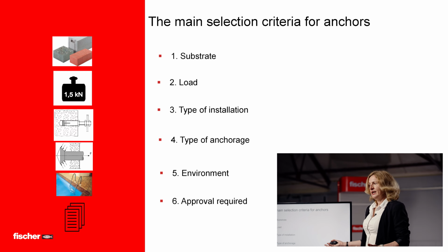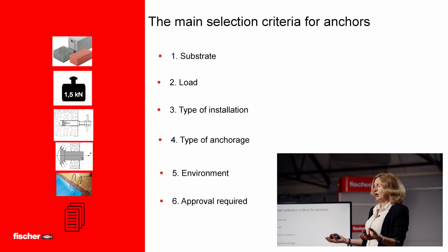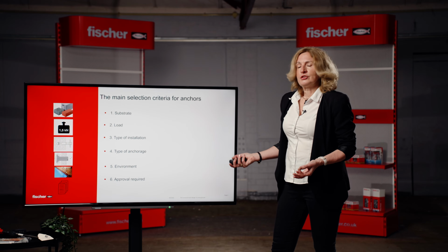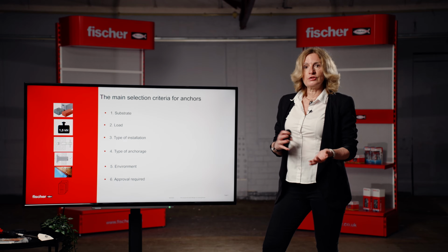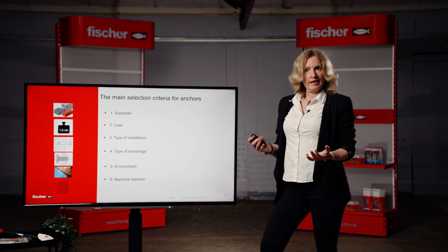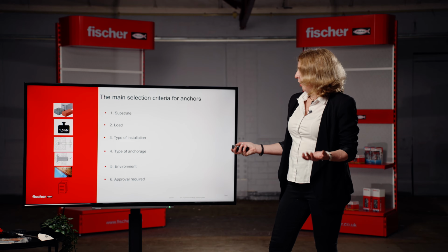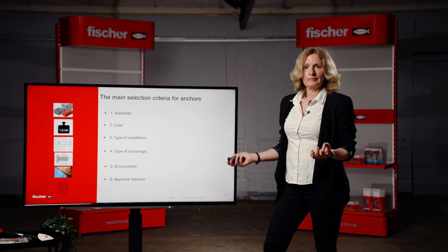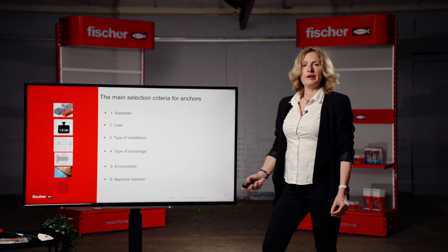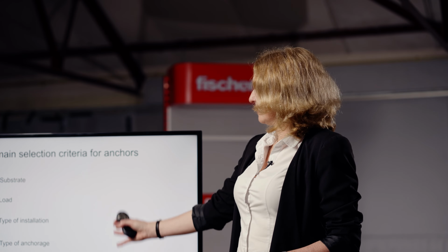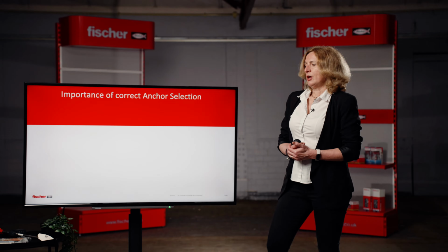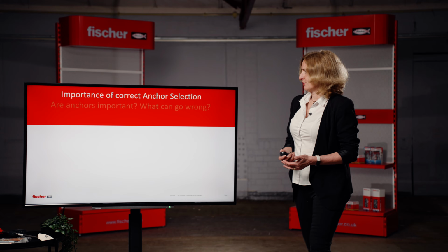Substrate, what you are fixing into, what is your load, type of load, is it static, variable load, fatigue load, dynamic load, type of anchorage, type of installation, environment, can you use plated anchors, do you need stainless steel, what type of stainless steel, and also what type of approval. All these factors are very, very important. We do have a specific CPD just focusing on these topics: importance of correct anchor selection.